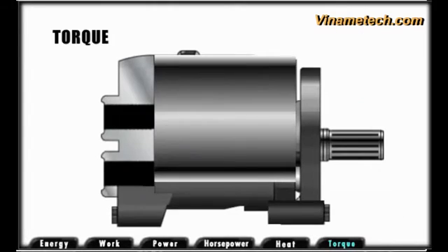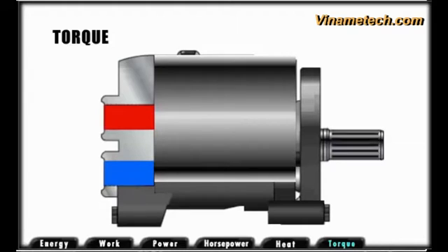This same theory applies to hydraulic motors. Hydraulic motors are actuators that are rated in specific torque values at a given pressure. The twisting force, or torque, is the generated work. A motor's RPM at a given torque specifies our energy usage or horsepower requirement.